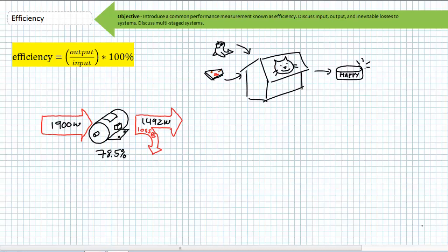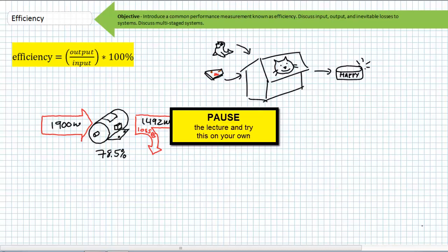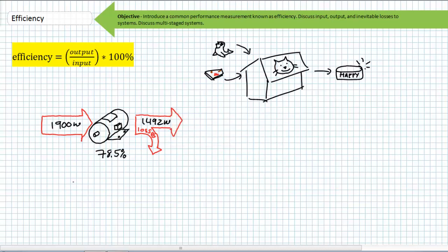Consider the collection of 2 horsepower motors used to grind up old gym mats and baby harp seals into cat food. See if you can calculate the energy consumption and cost of running a motor over the course of a 40-hour work week for 52 full weeks. Let's assume the price of electricity went up and it's 15 cents per kilowatt hour now. Okay, remember, energy is power times time.